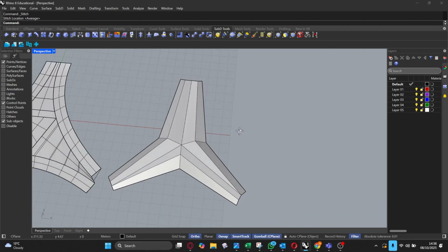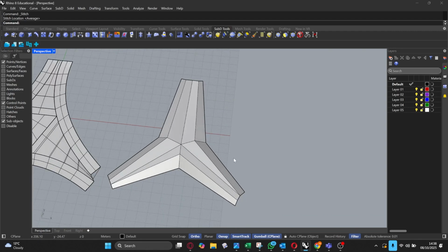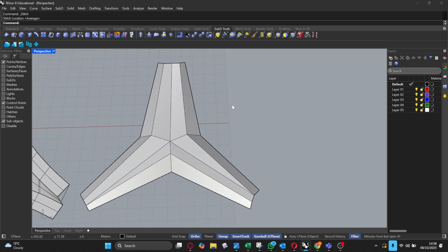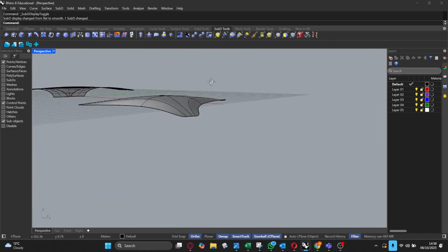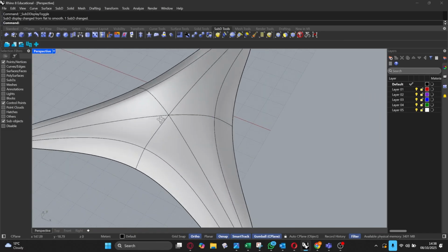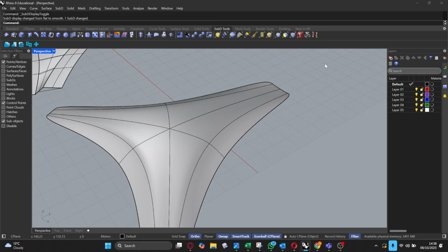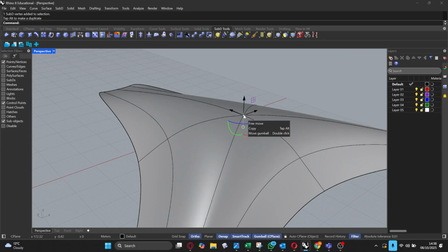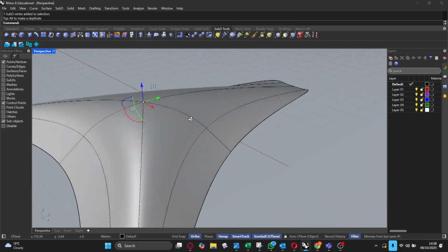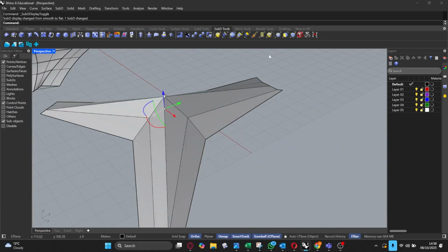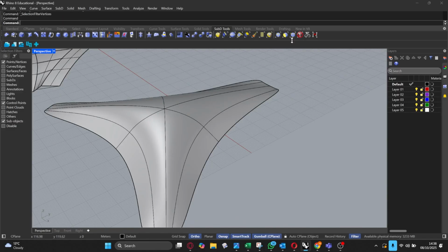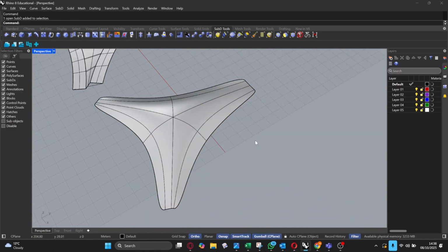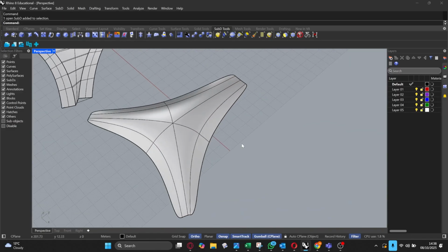So now we've just cleaned up our geometry with just a few moves to create quads. And we'll see how much smoother that looks now than before, because we have a little bit more control over this geometry. Now we have this point here, which then makes a much smoother surface. So well done. That's a really important rule, everybody. So remember that. Please remember that.